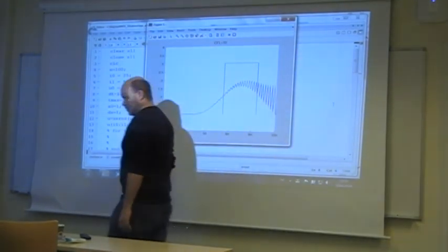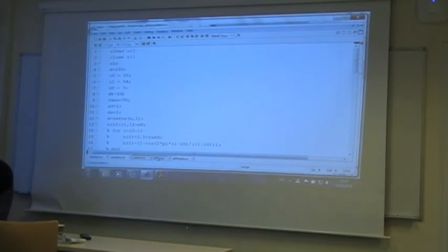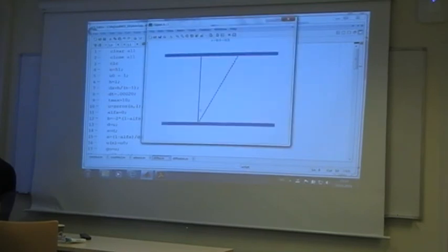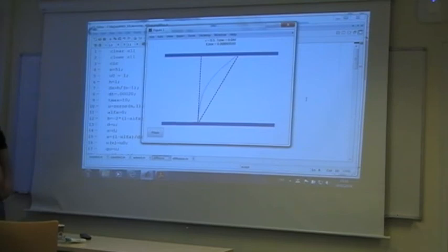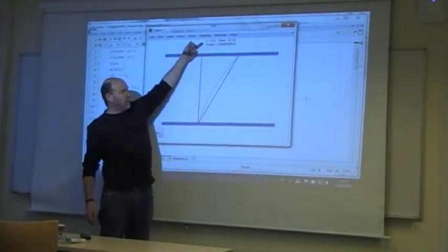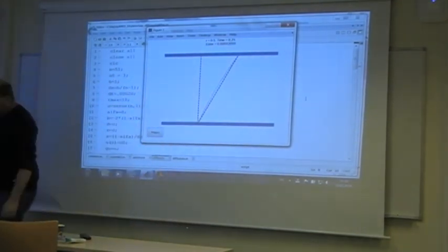This was the advection problem. If we go back to the diffusion, should be here somewhere. Now where did we leave off there? We had a fully explicit scheme, and if we had the stability limit, this ratio R should be smaller than 1/2, then it was stable. So here it is stable, that should be okay.